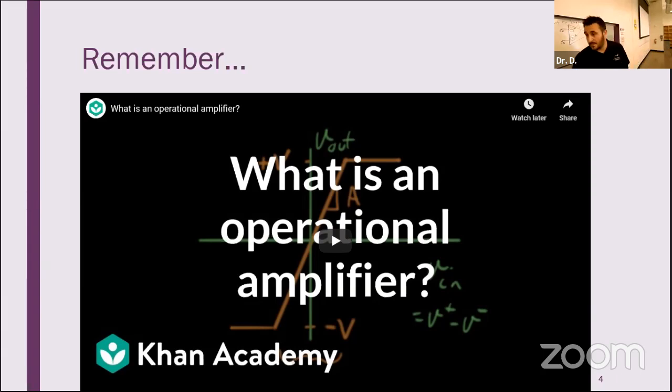Those are the two op amp truths that we really need. The third one is that the gain is infinite, but that doesn't really come into play the way we're doing our analysis, and it falls out as a function of the other two truths.